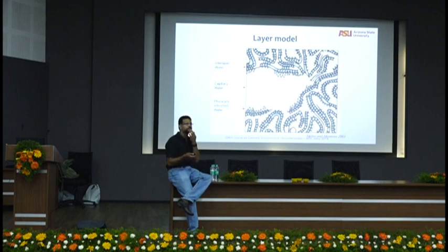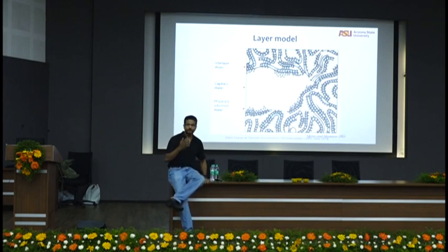Okay, so when you want to measure degree of hydration, you want to measure how much of the cement has hydrated, right? So you do non-evaporable water for degree of hydration. Have you done that? If you do non-evaporable water for degree of hydration, you're looking at how much of the water in this system is non-evaporable, which means how much of the water will go away only if you heat it to a very high temperature. At the boiling point of water, now there is another physics behind this.